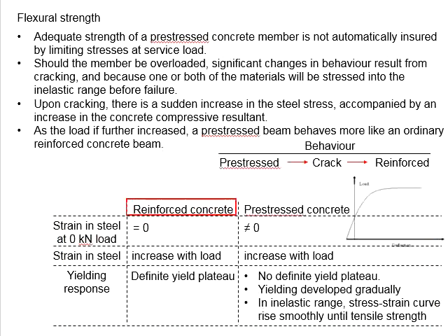First, a typical reinforced concrete beam has no steel stress developed in the unloaded condition of 0 kN load. However, for prestressed concrete members, there will be stress, which gives it negative strength at the condition of no external load. Then, when the member is subjected to external load, the member deforms and the stress in the steel increases with the load.